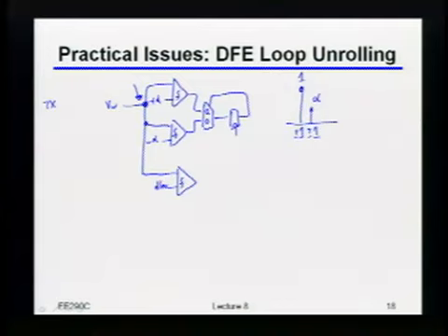So now I know I said before that this looks kind of weird, but now we're actually going to go ahead and draw it. Let's see what the eye diagram for something like this actually looks like, okay? So in some previous data sample, and I'll draw it a little bit bigger, I could have had 4 possible data levels. And of course, in this data sample, I could also have 4 possible data levels. Okay, but now, what transitions am I allowed to make? So let's say that I used to be at this upper data level, which remember is just plus 1 plus alpha. From there, where can I go? What could the next value be?